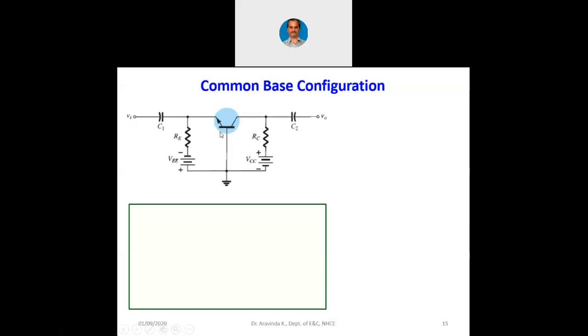Current into the emitter will not go at all, because we have biased the circuitry in such a way that base to emitter junction is forward biased. So DC current is always going out of the emitter itself. That way the working of the emitter is not affected. But we keep the transistor in half on region. Later on we apply AC input. Then only the switching of the transistor is slightly affected towards saturation or towards cutoff. That is when we take the output at the collector.